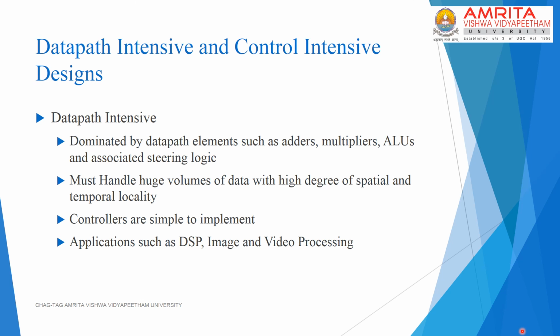In datapath intensive designs, most of the hardware will be dominated by datapath elements such as arithmetic circuits and registers, and associated steering logic like muxes, decoders and demultiplexers. As far as the nature of the data that flows through these systems is concerned, mainly these are continuous streams of data which have a high degree of spatial and temporal locality. This is a trait that we usually observe in applications such as DSP, image and video processing.